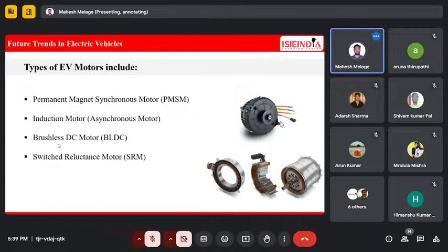So now we use another converter, which converts DC to AC. Let us assume a PMSM motor is used in a two-wheeler. What parameters can be added? We use the charger to convert AC to DC. We use the battery to store the charge, and then we use another converter to convert DC to AC. Why? Because the motor is AC supply operated. So another converter is used.